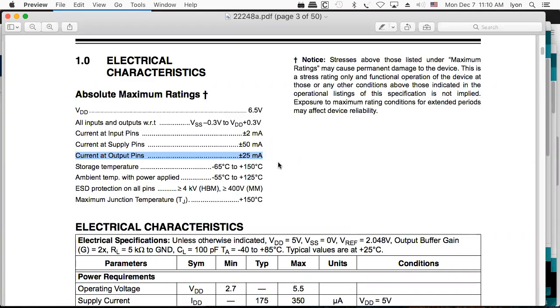Well, wait a minute. 8 ohms, E equals IR. E is equal to 1 volt, and R is equal to 8. And so if I take 1 and divide it by 8, I should be able to get my current, which is 0.125 amps, or 125 milliamps. And this thing is giving me 25 milliamps. And this is why I say, for your basic 8 ohm speakers, there's no hope of being able to drive these things at reasonable volume.